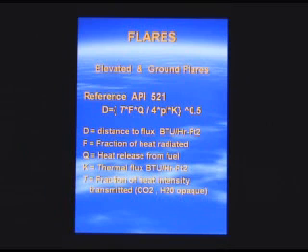The K value is a value that you would input. Current practice is to use 500 BTU per hour per square foot as a thermal flux from a radiant flame. API says that you are able to survive in that environment with reasonable clothing, and that K value would also include solar radiation.